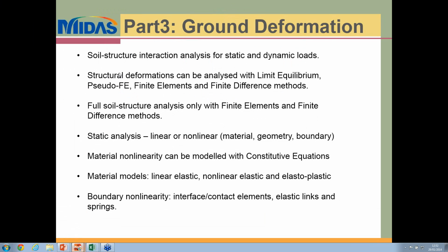Then in the third part, for the ground deformation analysis, the soil structure interaction analysis can be performed for both the static and the dynamic loads. And for the deformations in the structural members, they can be analyzed either through the limit equilibrium solutions, or you have the pseudo FE solutions, finite elements, and finite differences. But the limit equilibrium solutions are handicapped in a way that they can't give you the deformations within the soil itself. They might give you the deformations and the forces in the structural members, but not in the soil. So to get the full picture in the analysis, you need to perform soil structure interaction analysis either through the finite elements or through the finite difference methods.